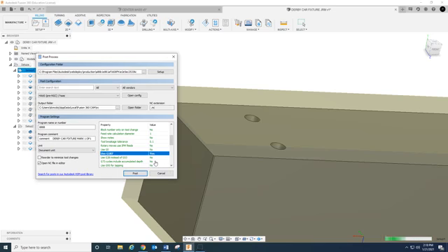G187 basically puts it in a mode where it tries to hold corners really tight. It slows it down a little bit, but anyway, I use it, and it makes the code a little bit cleaner. And then there was one other one, the sequence numbers. I do not use sequence numbers. They eat up a ton of memory, and they just make the code cloudy. No, if you like sequence numbers, use them. No issues there.